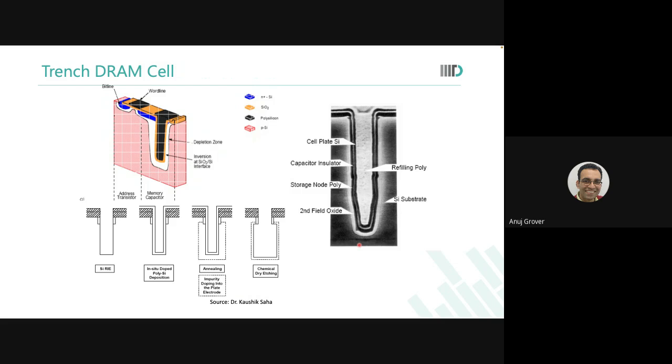The challenge with trench capacitors is that at that nanoscale, you have to drill a deep trench inside the substrate. You have to actually put an atomic layer of metal, then an atomic layer of dielectric, and then fill the remaining trench with the next metal. And they do that fairly well. They really do that fairly well. But the challenge is, how do you scale this?